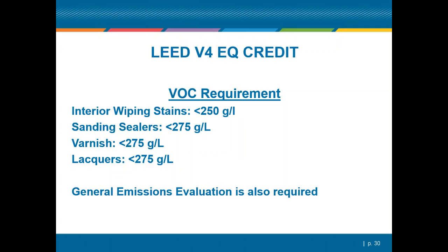Once you pop the lid off the top of it, it's pre-catalyzed, and whenever it's applied to the surface to dry, there's a catalyzation aspect that goes along with those products that makes them more durable than a non-catalyzed product. Now, if we're talking about two-component products, you normally have a part A and a part B. You blend those two products together, and there is normally a dwell time, maybe 10 to 15 minutes.